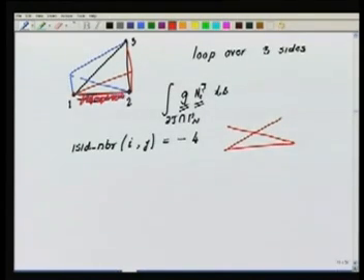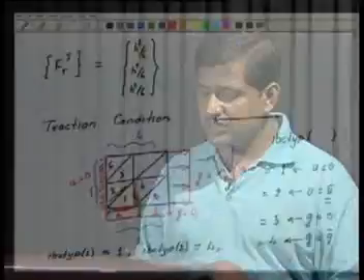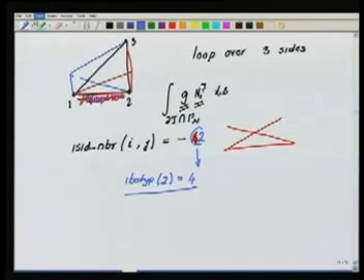Now what we are saying here is, let this G also be a constant. Here, as a simple case, we are taking the G to be constant on this edge. So let's say if I am talking of the element 1, then I find that the first edge of element 1 lies on a boundary which has, sorry, I made a mistake here. The side neighbor is negative. Okay, so here I have side neighbor is -2, -1, whatever, but only when the IBC type for this particular boundary is equal to 4, then only I am interested in this boundary edge, otherwise I am not. So I made a mistake in transferring the data. Okay, so only when the IBC type is 4, then I am going to do the integrals on this edge.